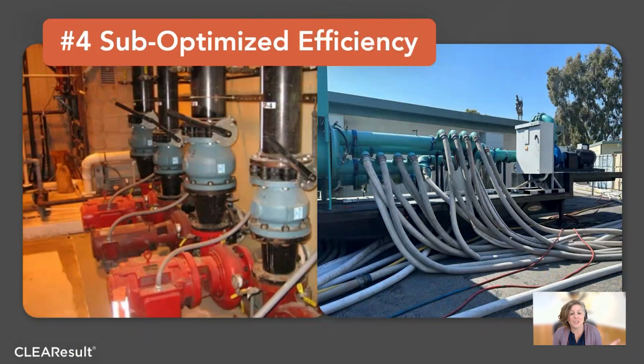Design engineers love their safety factors. Most systems are designed at the very top of the flow. So if, for instance, we have all these pumps here, there's 4 pumps. That system was probably designed for a lot of pumping, but they don't need that. They have throttled almost all of them down pretty substantially if you look at those throttles.